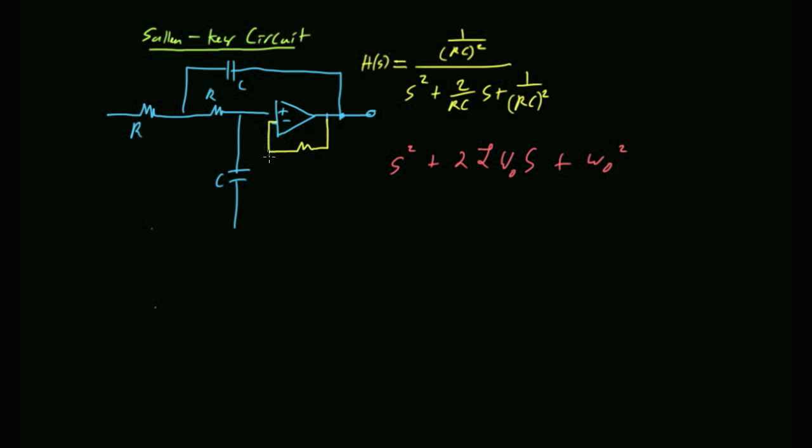You guys remember that circuit? What is that? It's a non-inverting follower with a little bit of gain. Okay, so I'm going to label this R2, and that R1. Just for this circuit, let's say that it has a gain. Does anybody remember the equation for the gain? 1 plus R2 over R1. We taught you this stuff for a reason, okay?